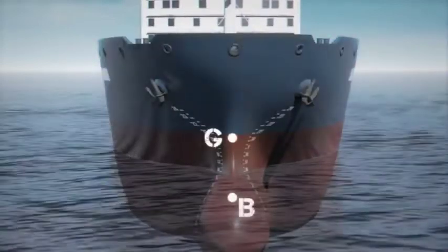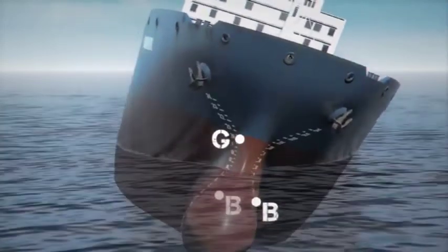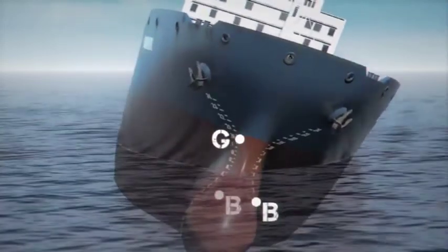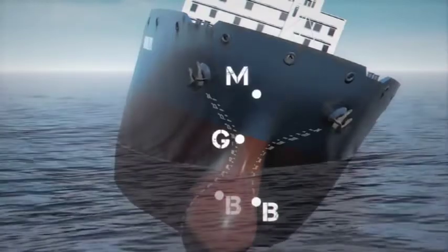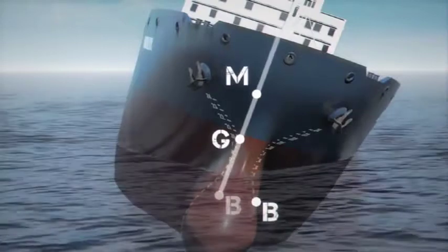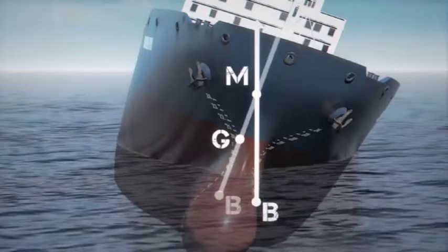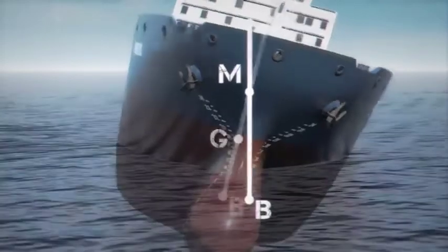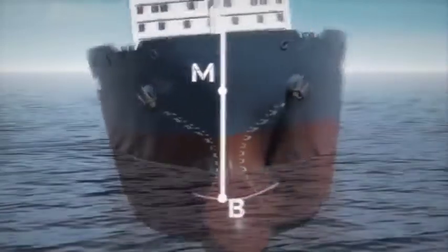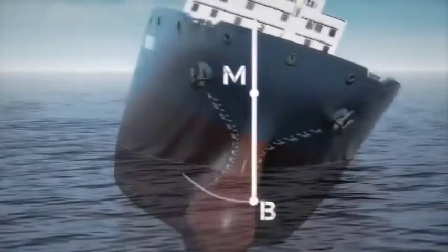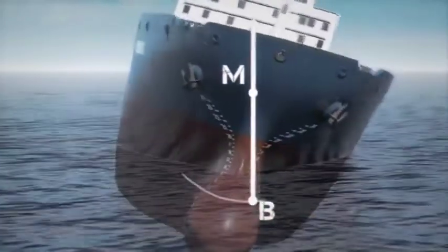As we've seen, when a vessel rolls, B moves in the direction of the roll and out from under G. The metacenter, or M, is the intersection of the upward force of B when a vessel is upright and when it is at an angle. Think of it as the center of the arc that B moves through as a vessel rolls in the water, like the anchoring point of a pendulum. It is considered to be on the center line at small angles of heel.